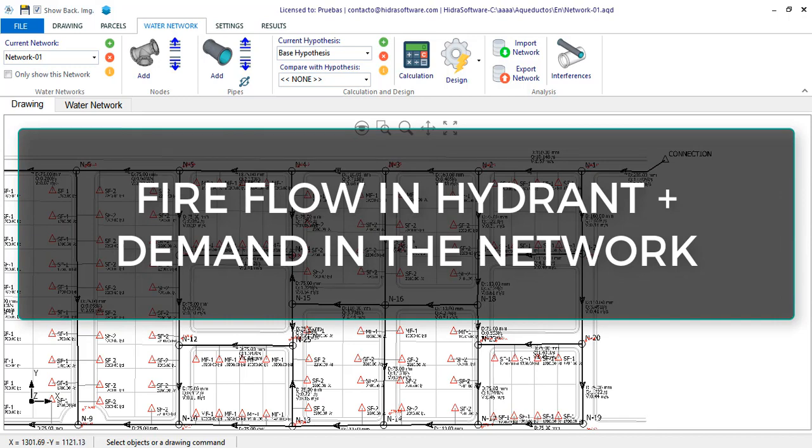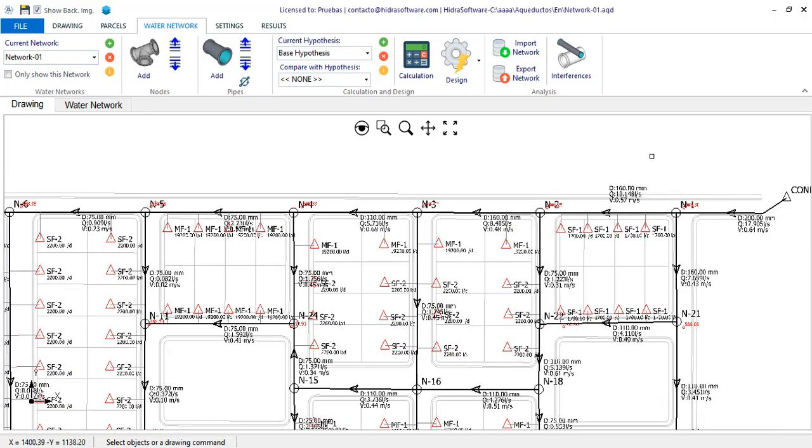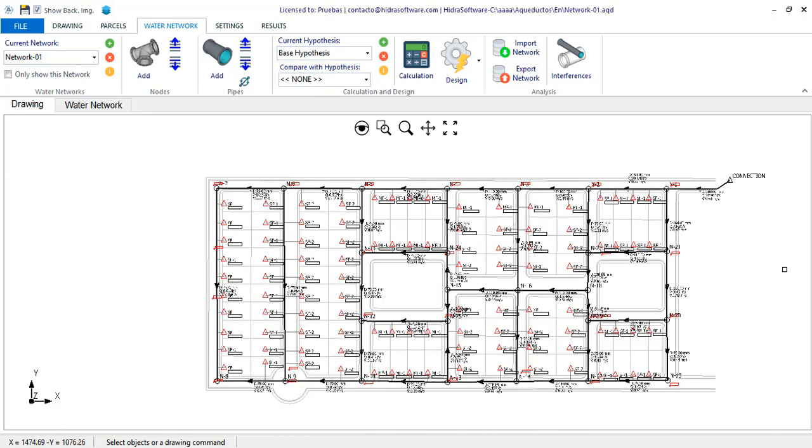In the rest of the water network's nodes, the demand is somewhat lower than the peak hour demand and is usually, as I have previously said, equal to the maximum day demand. The water network verification under this second hypothesis must, in order to consider the design valid, result with pressures again within a range, and it is also necessary that the pipe's flow velocities do not exceed a certain value.